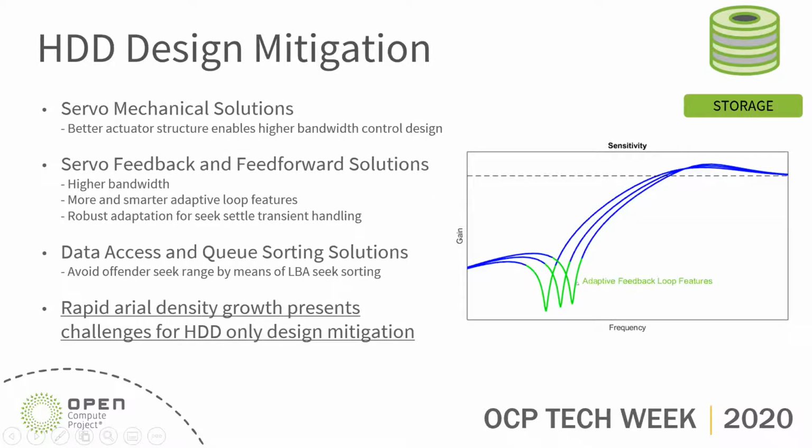An example is shown here. Since it's just one frequency ringing in most cases, you can design an adaptive notch which would search for this ringing frequency and target it particularly and adjust as needed per system or per case.